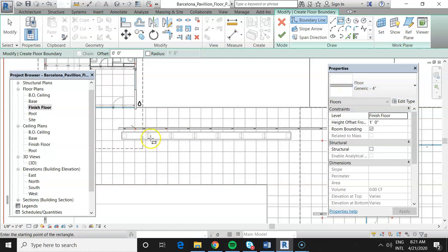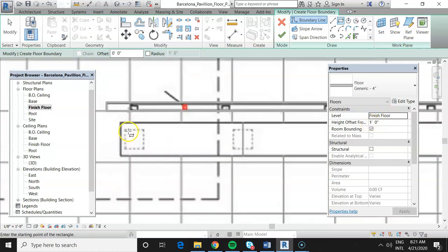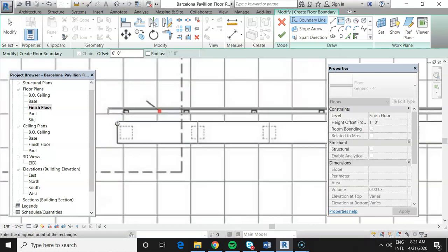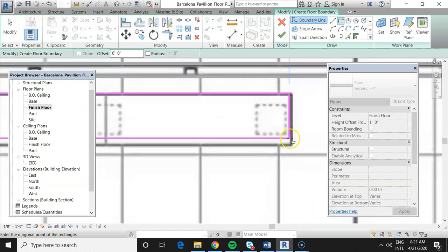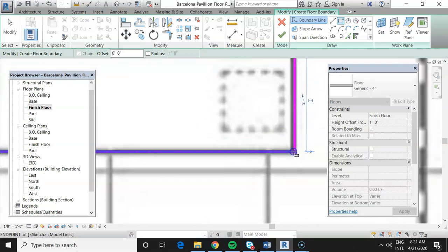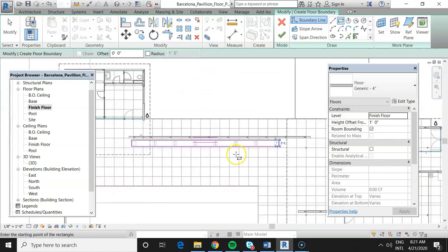So we want to place this here, and we want it to be 16 inches. The top of it should be 16 inches above the finished floor. I think the height offset is, for some reason, set correctly at 1 foot already. So the 1 foot plus the 4-inch thick floor should get us 16 inches above the finished floor. So that's where we are: finished floor plus a height offset of 1. We'll, of course, check this out in section to make sure that I am correct. And we always like to zoom in and be nice and careful. Okay, so that should be that.